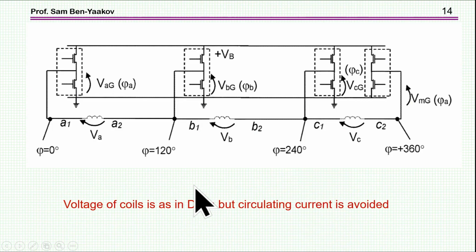So here it is, the scheme. We have the 3 coils. We have a half bridge, which is kind of the reference, and then we have a half bridge which is operating with the first half bridge to generate a current which is sinusoidal, and this is the reference current. And then I have another half bridge which is working with this half bridge to generate a current which is of the same magnitude as here and phase shifted 120 degrees. And then I have a third half bridge which again is controlling the current here with 120 degree phase shift.